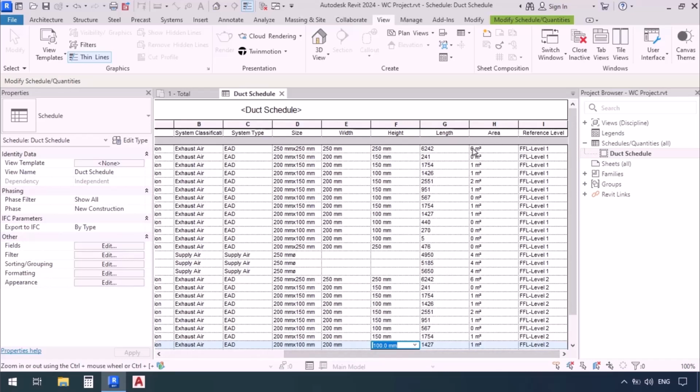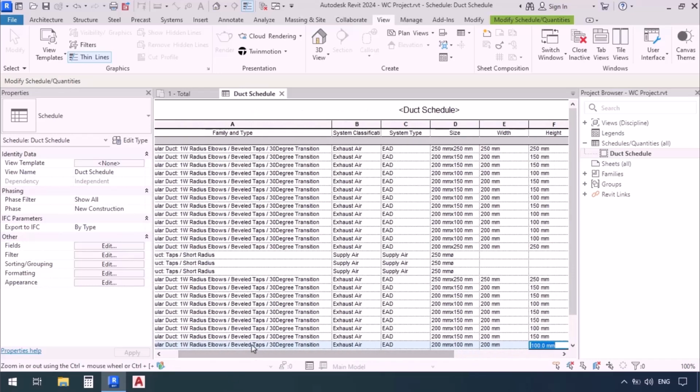As for the area value, since it has been rounded to a clearer number, it shows only 0 at the moment. It could be 0 point followed by several numbers, but since that number was rounded, it shows 0. We could readjust some settings about this area so that it shows the exact values with their decimal places. Alright, so in the first step, we're going to remove the width and height.